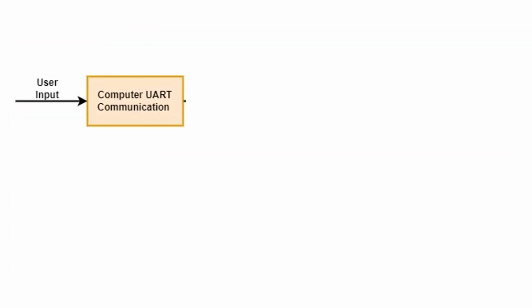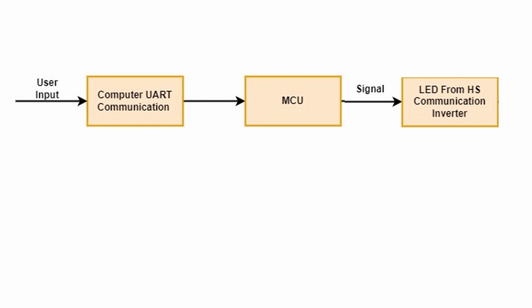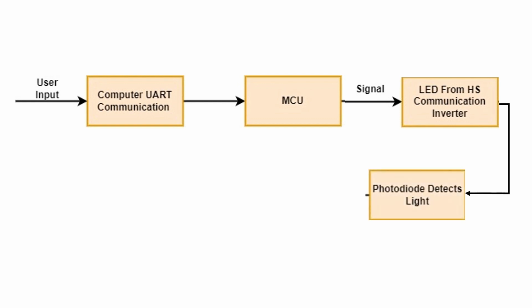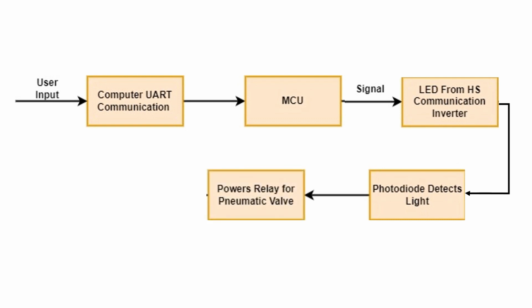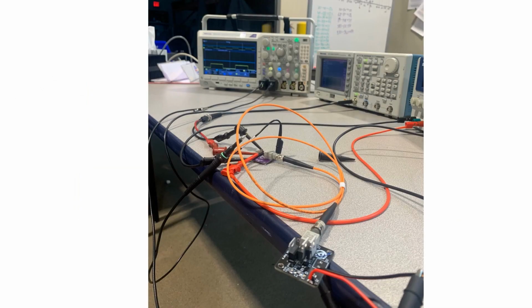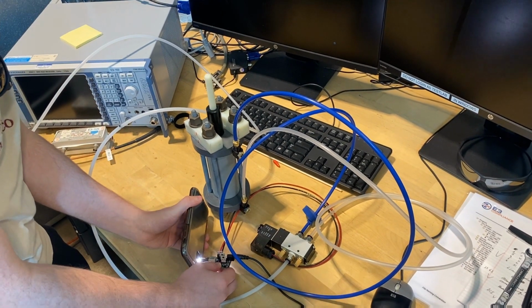The MCU receives input from the test technician regarding whether the arm should be in the vertical or horizontal polarization, and this electronic signal with that information is converted to a light signal with the transmitter PCB. The signal then travels through a fiber optic cable to the receiver PCB inside the chamber, which actuates a pneumatic device that pushes air into the double-acting hydraulic cylinder from either the top or bottom, causing the arm to move either vertically or horizontally.